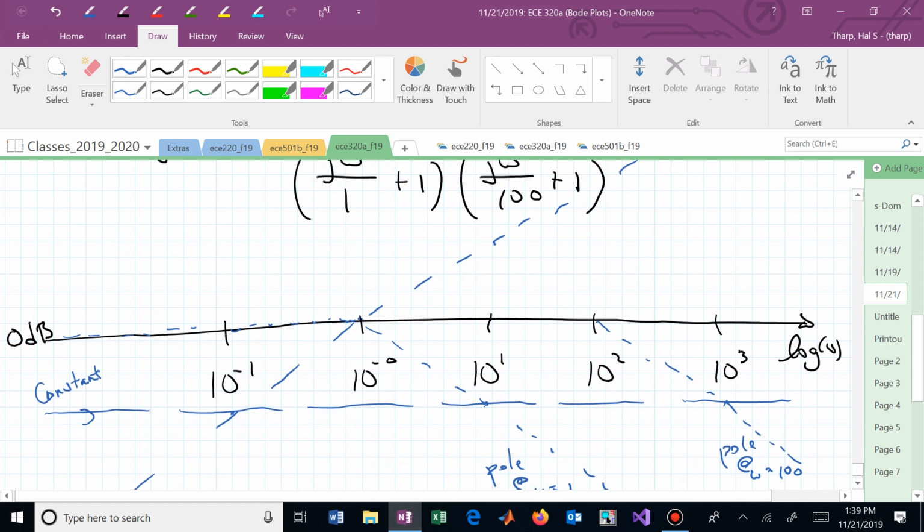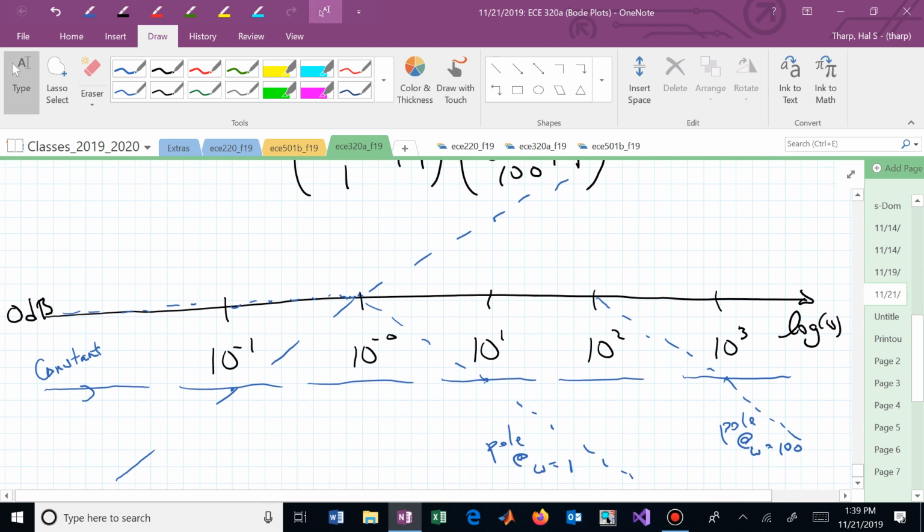And it's now sloping down at 20 dB per decade. We now simply start far enough to the left, far enough in low frequencies. Maybe I should do this for you guys. And then work our way across, trying to incorporate all of the different breaks and slopes as we go.